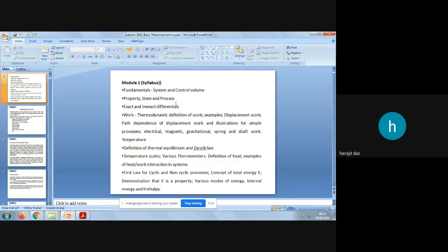When you plot all these points, you will see that all the points are thermodynamic equilibrium points, so you are able to join all these points by a distinct line. This means that from 27 degrees centigrade to 32 degrees centigrade, one process happens. That is why you are able to join all those thermodynamic points. This process is also called a quasi-static process, meaning a number of thermal equilibrium points will be there on the process line, whatever line it will be. In the PV diagram I have shown you how the process will happen.